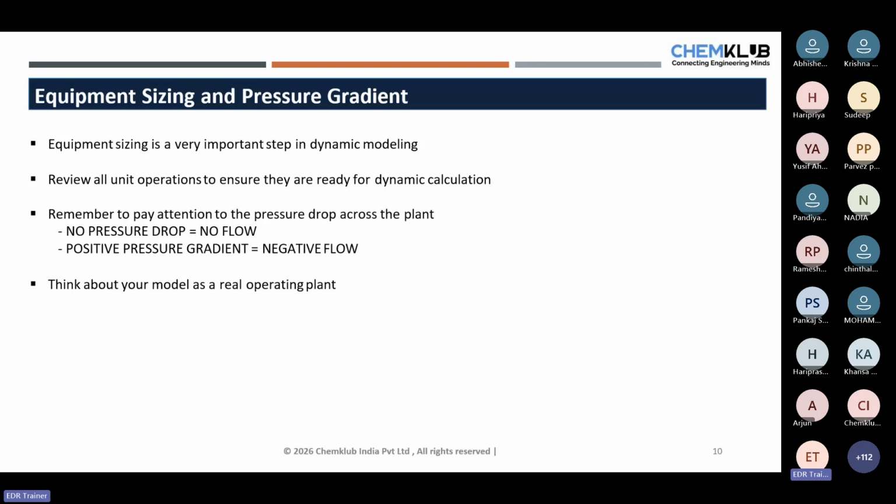Then the next step is basically the sizing of the equipment. So as I said, there are three things that are very important. One is that again you have to have a pressure drop. So that is an important thing. But apart from that, the volume is also important. Now, why is volume important? Because the volume decides how the system is going to respond to a change.